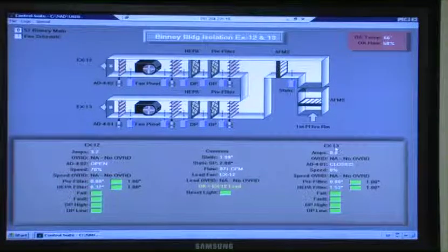Lead feed. Right. But the lag fan, all of these exhaust fans, anything that lead lags, the pumps, the fans, they're going to stay on for like 2-3 minutes to prove that the other one is on. Yep. So on a pump, like on that 5 and 6 heat exchanger, you're not going to have the lead pump on a changeover shut off and have no pump until that other drive comes on. You've got to be running both of them, and then the lag will drop off.